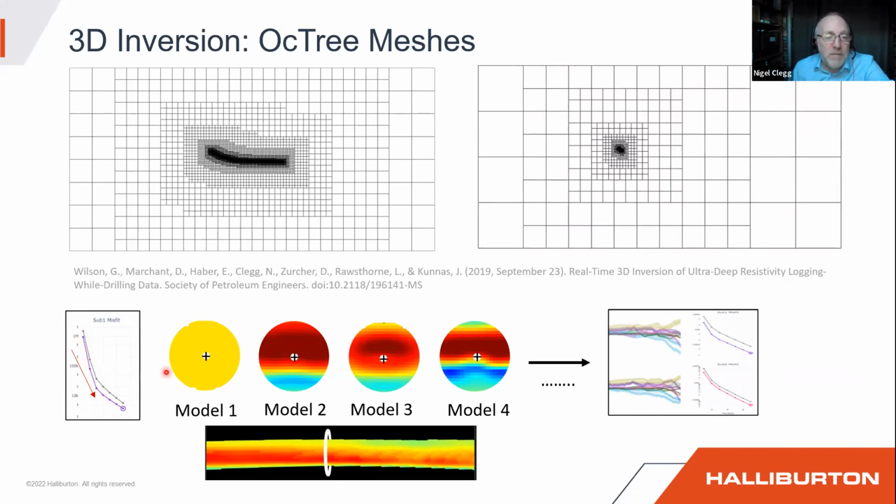So our first model is a representation of the whole space. Everything looks exactly the same. Then the second model is quite a simplistic representation of a high resistivity block and a low resistivity block. And this gradually gets refined as you get closer and closer to the lowest misfit. Now, this is a slice through the inversion, but in fact, this is a three-dimensional inversion that it's doing. But I'm just representing an individual slice to show you how that model gradually improves.